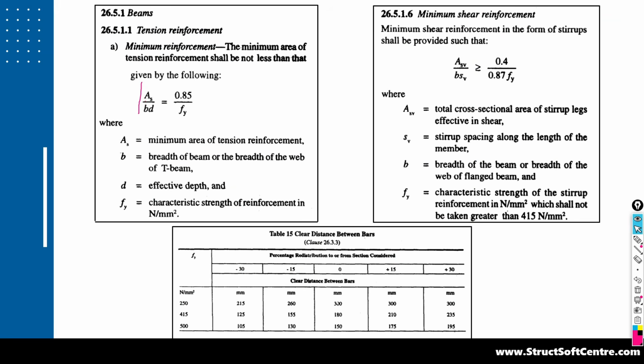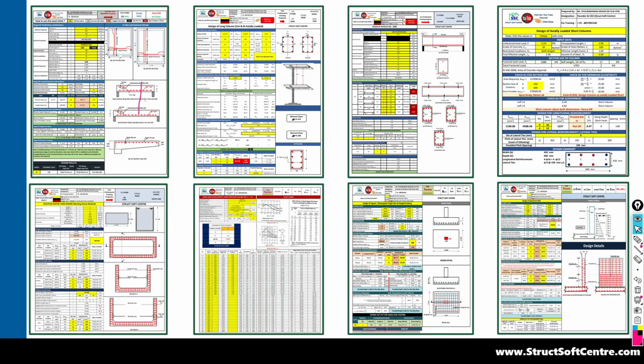And thereafter we need to see whether your ETABS software is following the code or not for doing the design, for finding out the reinforcement for the beam, for the column, whether the spacing criteria is followed or not. So all those checks, all those designs we can do with the help of a spreadsheet. So guys, any project you cannot do without taking the help of a spreadsheet. At different stages we need the spreadsheet for load calculation, for design validation, or some elements we are especially designing with the help of a spreadsheet.